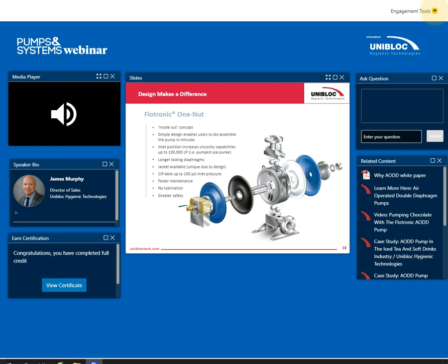Okay. Another question, what is the maximum air supply pressure used on this pump, and do I need an air filter or regulator? A filter lubricator regulator is always recommended for any type of air-powered equipment. It regulates air, but it also lubricates and takes out the particulate. So we recommend something along those lines. Oftentimes on your more industrial compressors they're built in already, but we definitely recommend the use of clean air.